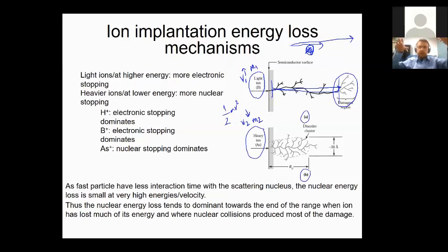and reacts just like an electron. It will start seeing all these potentials applied on it. So it will start hitting the silicons more and more frequently, and it will damage the crystal there. As for the arsenic, at its starting point it doesn't have that kind of a velocity, and it will start interrupting the crystal structure already initially.